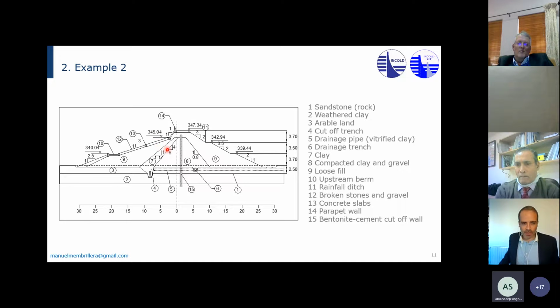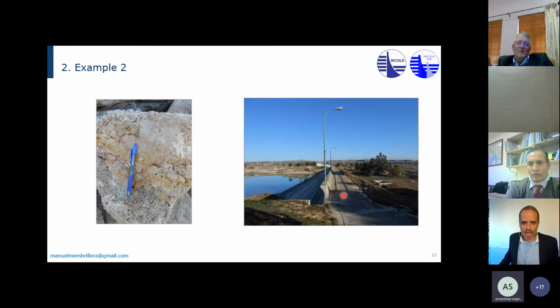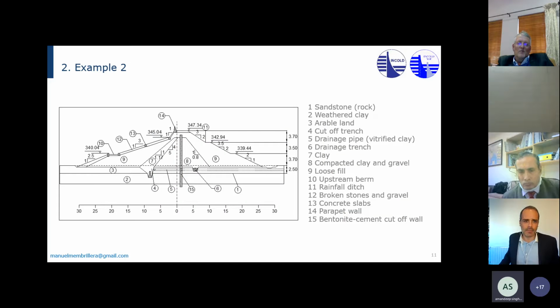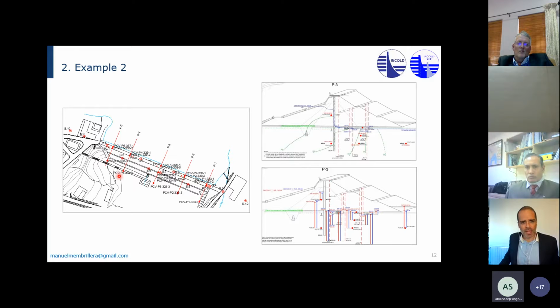Then in the early 2000s, when I started working at the dam, there were a lot of trees at the crest. We chopped them off. So you can see there are no trees now at the crest of the dam because we removed all those. And then these are the profiles that are monitored. And you can see here how the piezometers, vibrating wire and standpipe piezometers, Casagrande piezometers, and just open full water level piezometers down here, were giving funny trends going up and down.